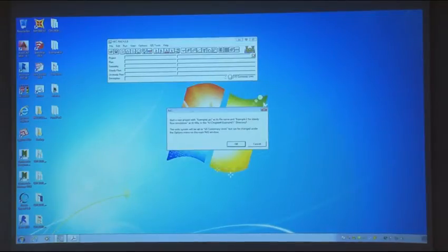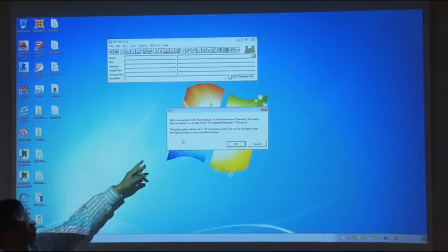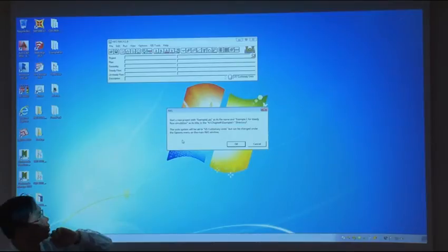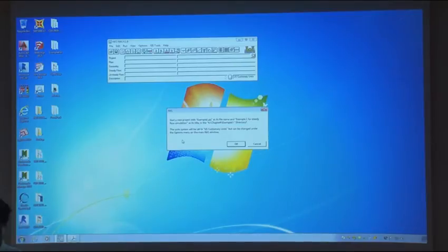Okay, it'll pop up a window for you. Start a new project with example1.prj as the file name, and "example1 for steady flow simulation" as the title. And in this H drive, chapter 4, example 1, whatever directory you select, okay? And also the next thing you need to pay attention to is that the unit system will be set as US customary units, but it can be changed in the Options menu on the main HEC-RAS window, okay?